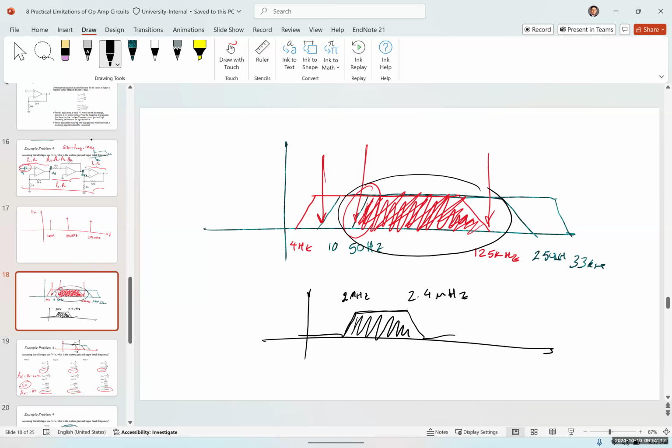We call this a bandpass filter. This is a variable filter. We can move it left to right. Imagine you have a knob, and that is actually a resistor potentiometer. Changing the potentiometer changes the impedance and changes the frequency. And imagine that you can actually move this to the left and right.